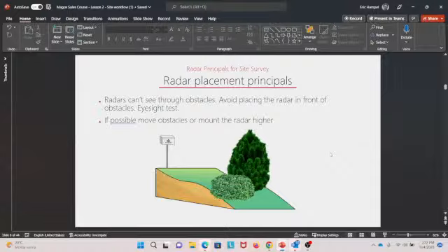So therefore, where will buildings be? It doesn't make sense to say everything's clear, the radar can be positioned at 4 meters, and once you start to install, in front of that position, you find an 8-meter high building. So therefore, updated information, clear positions of existing and planned buildings, and then in accordance, where to position which areas are good for a clear line of sight.